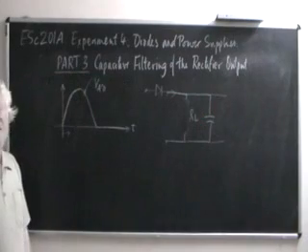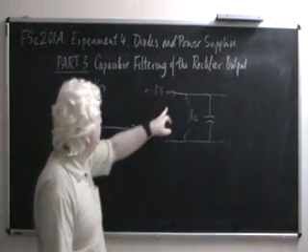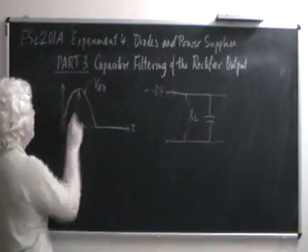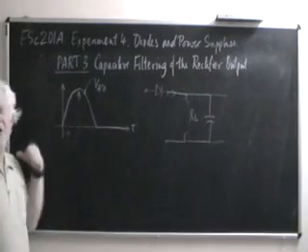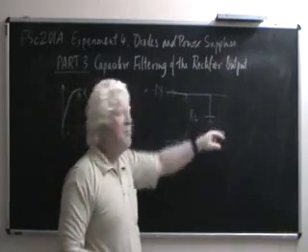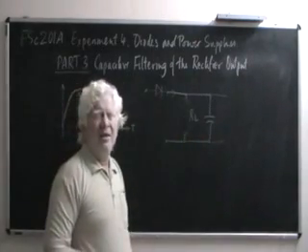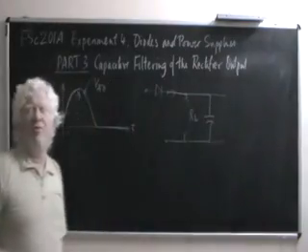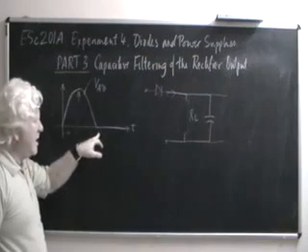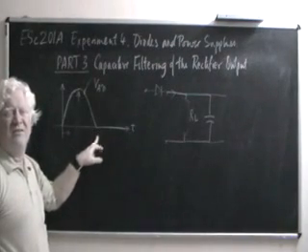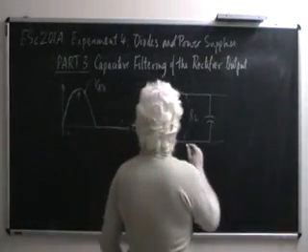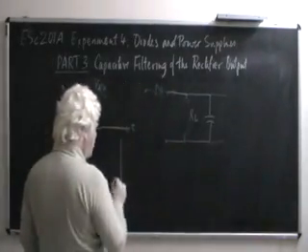In short, the diode stops conducting at this point itself, because after this, the anode voltage becomes lower than the cathode voltage. The cathode voltage is being maintained by the capacitor, whereas the anode voltage has started falling. So the diode has got reverse biased at this instant rather than at this instant as was earlier the case. So essentially, the diode has only conducted in a quarter cycle.